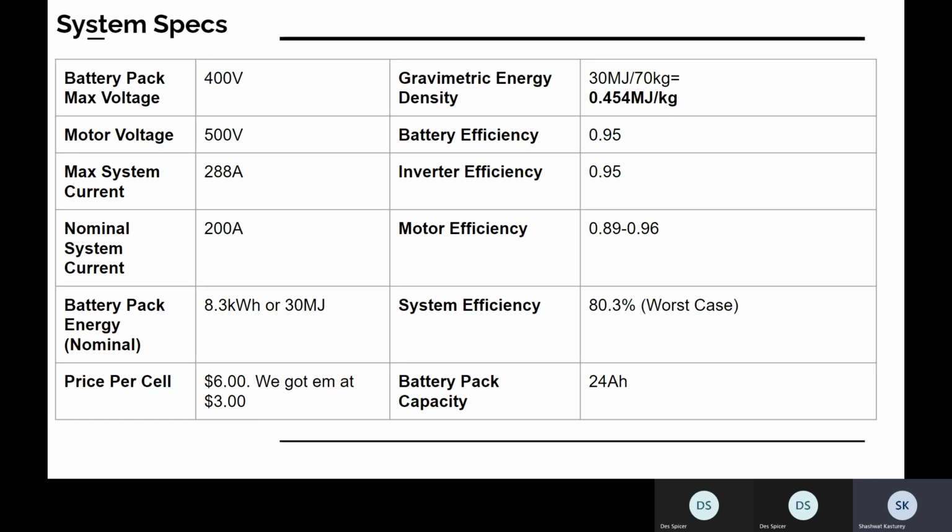If you take that quantity, 2.5 times 96, and you take 80 kilowatts and divide by that quantity. Sorry, this is a harebrained explanation. I really should have done this in line math instead of just a table. But anyway, take 80 kilowatts and divide it by the sag voltage, you get 288 amps of current draw, which is much higher than what we usually say is the nominal system current.